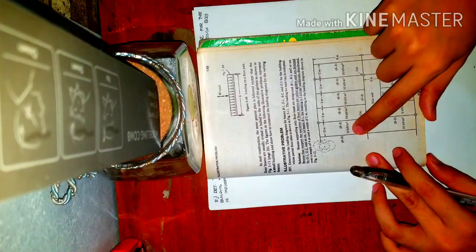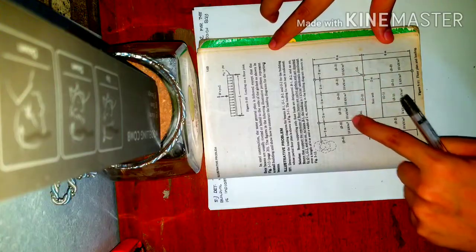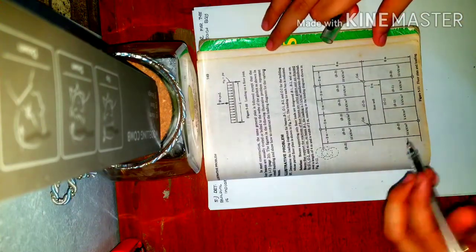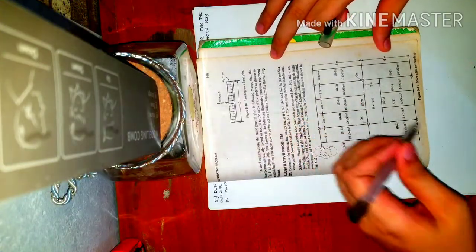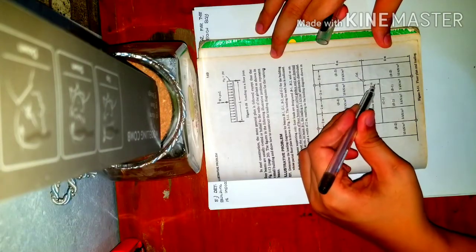Okay, so let's start. Let's solve some sample problems here. Problem 537, illustrative problem on page 149. This is our diagram, the figure of the floor plan with corresponding loading. The floor load pressure is given: here you have 10 kilopascal, and here 10 kilopascal, 10 kilopascal. And along B1, you have 5 kilopascal. As you can see, the columns are positioned there, the circles with an X. And in the middle, you have a stairwell.